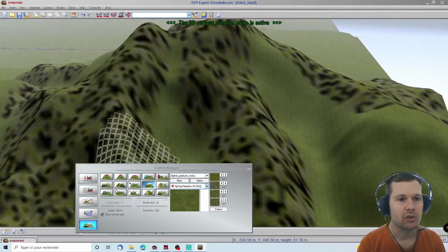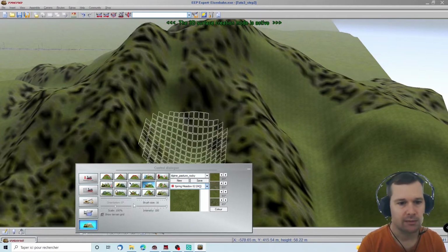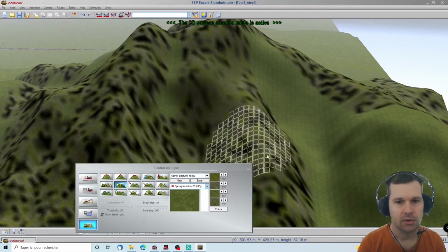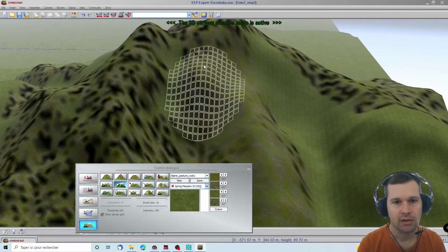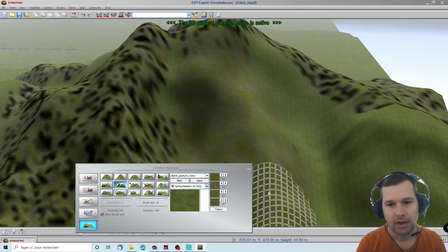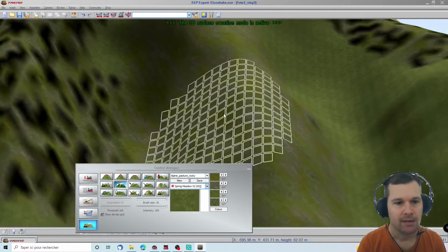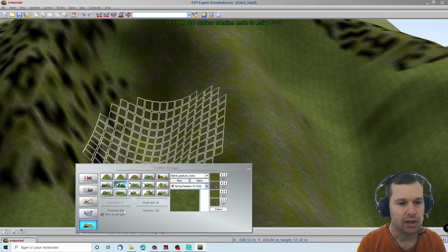Oh yeah, I forgot something. Here, don't make here scale 100%. I'm showing you why. Here I'm removing here the shadows. Have a look here. If you apply at 100%, it always looks the same. The best way for the texture is to have them here set on random.